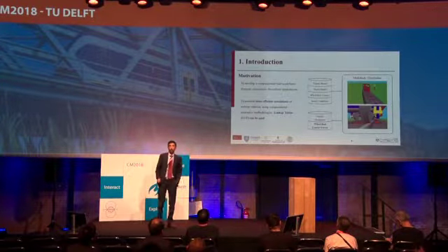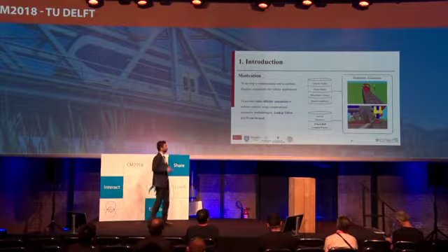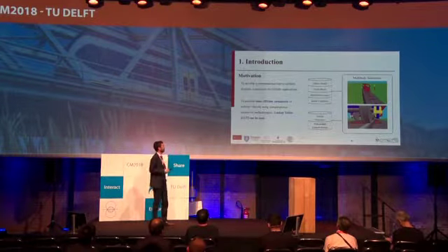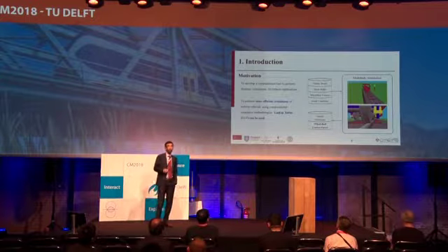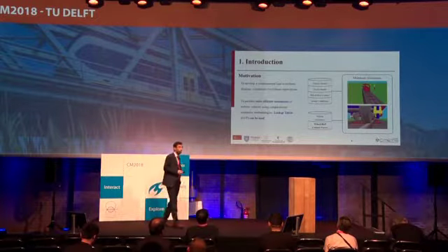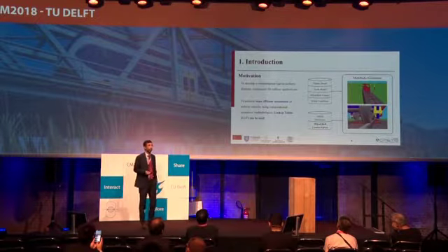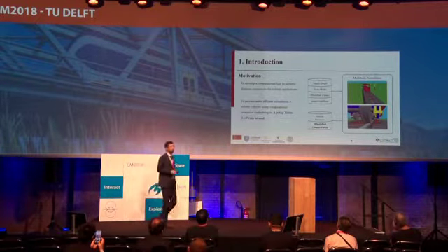The motivation is when we are interested in developing and using a contact model in the context of rail vehicle dynamics simulation and simulation of train-track interaction, then most probably we are not interested in going into the fine details of the distribution of normal and tangential stresses in the contact patch. We are rather interested in a good description of the total forces and spin moment that arise from the wheel-rail contact condition. And then we have different alternatives at hand, all representing in some way a trade-off between accuracy and the computational effort involved with the calculation.